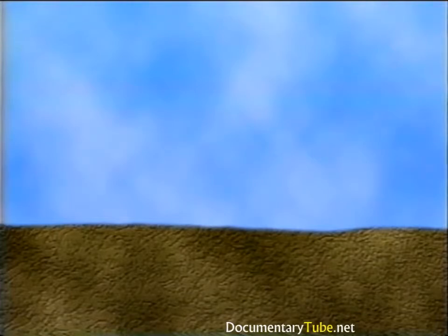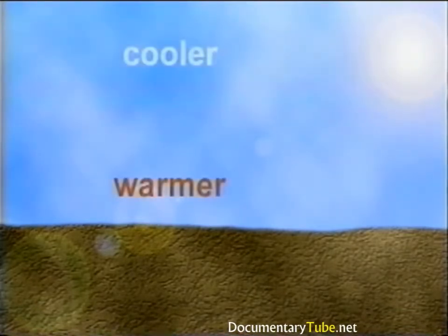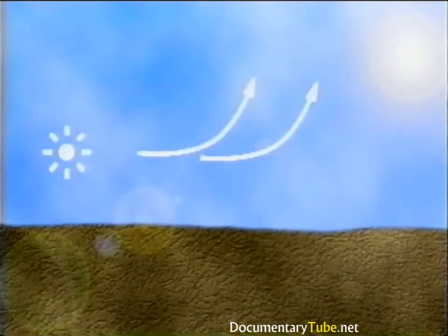Meteorological conditions can also affect the direct propagation path. These conditions include vertical temperature and wind gradients. In general, daytime weather conditions permit the ground to be heated by solar radiation. The air nearest the ground is warmest, becoming progressively cooler with increasing height. This is called a temperature lapse. The speed of sound increases with increasing temperature. This causes sound rays to bend upward away from the earth. In turn, the noise level at the receiver decreases.